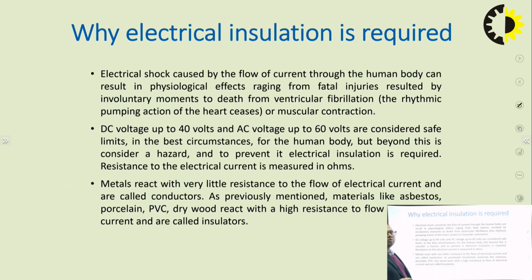Then why is electrical insulation required? Electrical insulation, I have already told you, is required in order to avoid electric shock or fatal injuries. For DC voltage, 40 volts is sufficient, and for AC, 60 volts is considered to be the safe limit in order to use the particular materials.